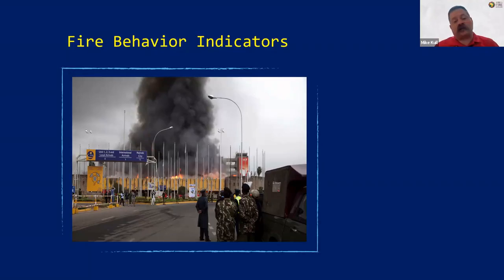And if we change that flow path with improper ventilation or something, we open some windows or some doors and create more intake flow paths, we're going to fuel the fire. If we make new exhaust flow paths, we may change the course of the fire and draw it into a part of the building that's not already burnt.